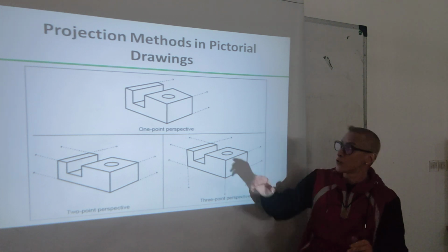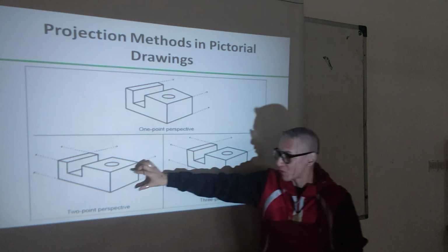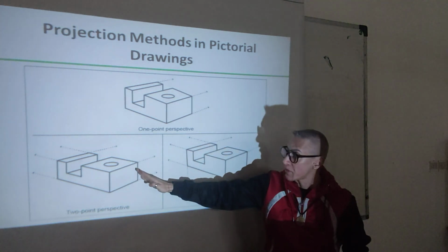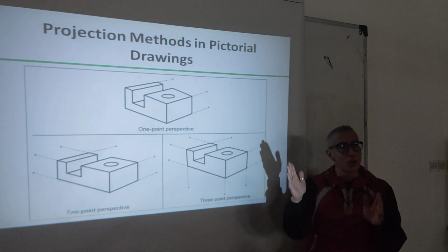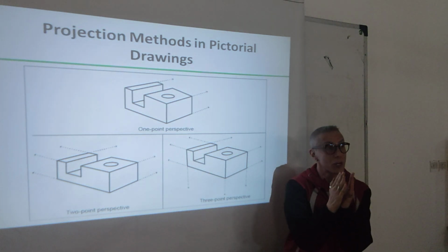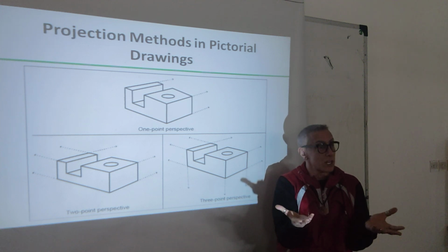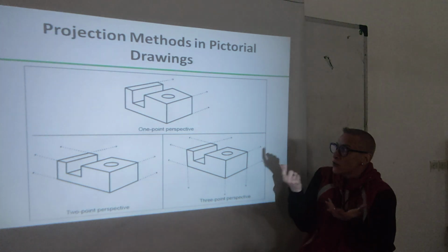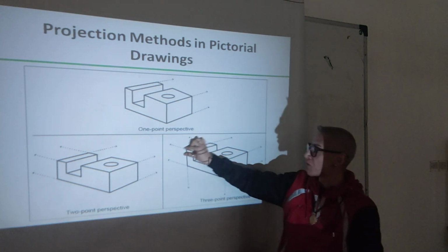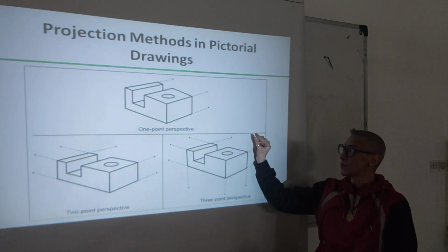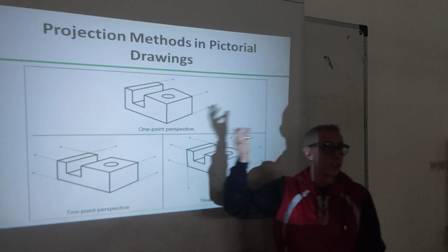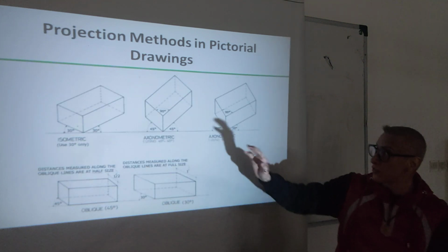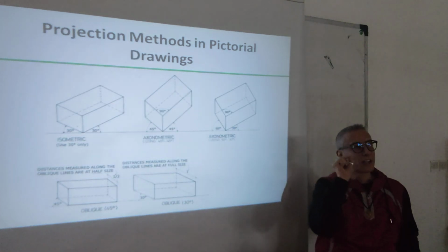Because when you have a perspective drawing, for example, going towards a vanishing point, everything going towards the vanishing point becomes smaller and smaller and smaller. It's beautiful pictorial, but it's not accurate. It's not used in engineering drawing, because we cannot visualize it. If I have something here, it becomes smaller and smaller, but in reality, this piece here is the same size as this. So it becomes confusing. While these drawings here are accurate, exactly, we know.